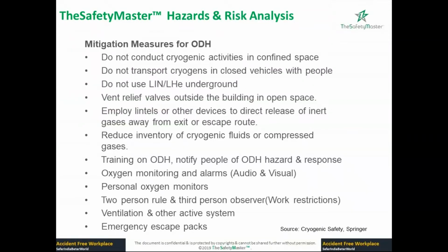Vent relief valves outside the building in open space. Employ a lintel. A lintel is an opening in a confined room, at the top, like a ventilation window. That should always be open for any inert gas to escape. Reduce the inventory of cryogenic fluids or compressed gas. Provide training on ODH and notify people of ODH hazards. And you should have oxygen monitoring and alarms, both audio and visual. It means it has to sound, and visually it will also show the danger.